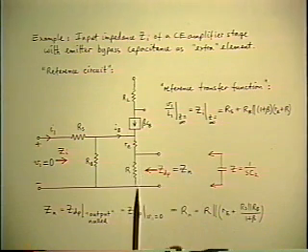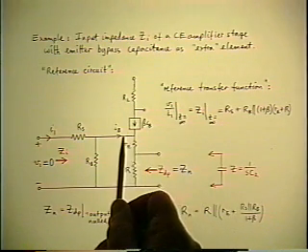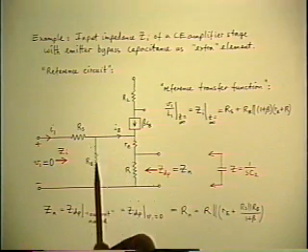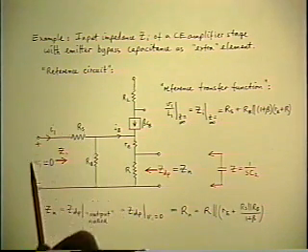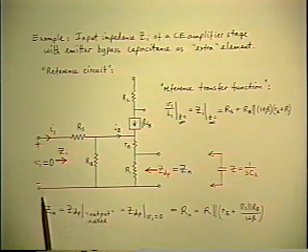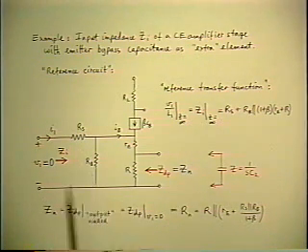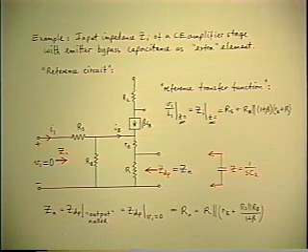Which is R parallel RE plus the reflected base resistance, which consists of RB and RS in parallel. Because if V1 is nulled, it puts the RS back in parallel with the RB. So that's the answer for the Rn.